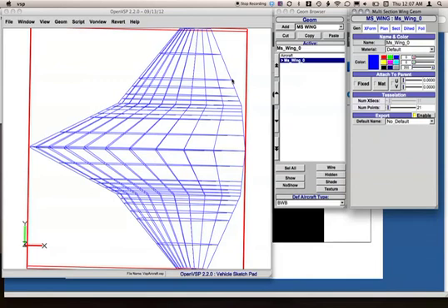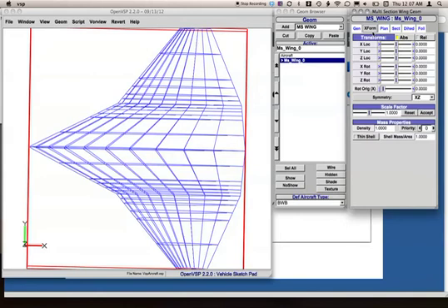And notice as soon as you add the wing, you end up with another window over here which provides your multi-section wing geometry. You can come in and edit that. And you'll notice it has various tabs as components of this. General tabs such as, I want to change the color, be able to change various other options here which we'll talk about later, we don't need to worry about yet.